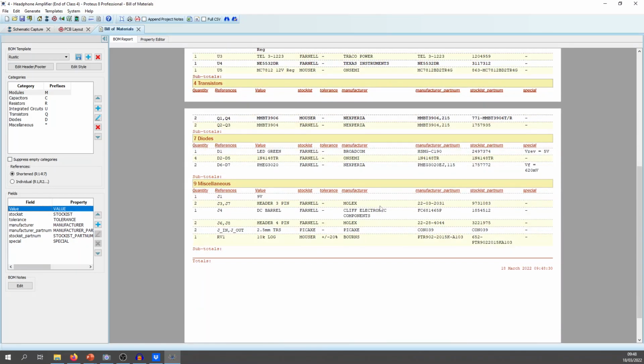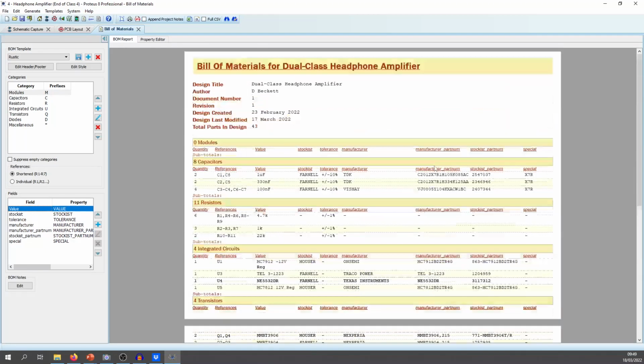The one thing that you want to check for when you're at this stage is, do you see anything on there that says not checked? You know that the script that we have, it has not checked by default. That means that you've not checked that particular thing. So if you've got any not checked on that screen, then you know that you go back into the part, check it, put a dash if you don't need it. But that's that. I mean, that's your BOM done now. It's literally, that's where a lot of that previous effort comes into play.